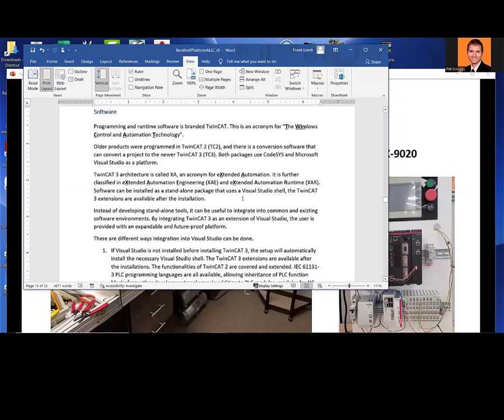So when you install it, it uses Visual Studio, and if you already have Visual Studio installed, it's going to install right over the top of your existing Visual Studio. Now, this can cause a problem. I had somebody do this at Automation NTH, and it kind of co-opted a lot of their extensions for previous products, and it tried to open them in TwinCAT, and he didn't like that. So he had to uninstall the software. I'll talk about some of the adventures I've had with the installations, and other people installing it at NTH, in a few minutes here.